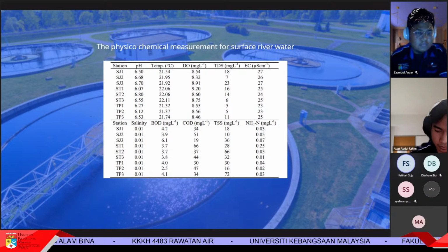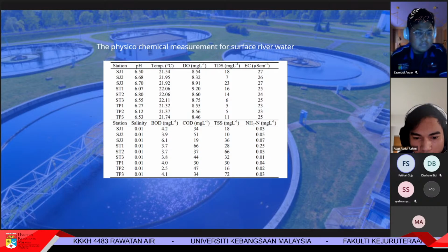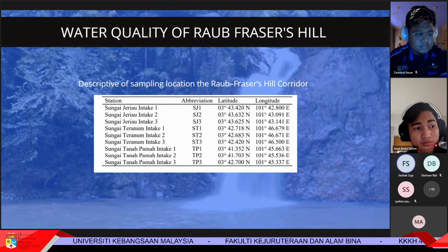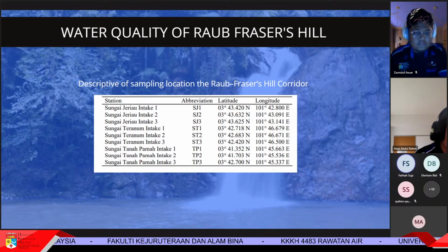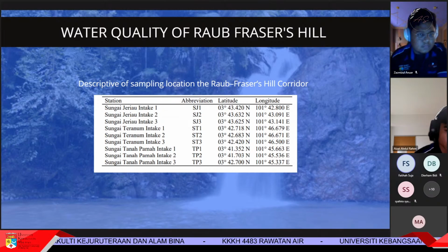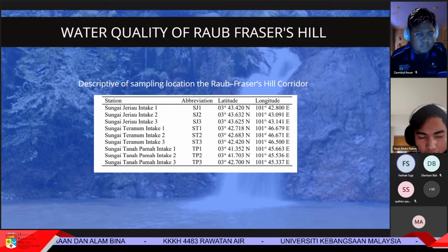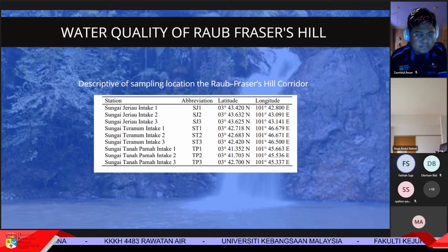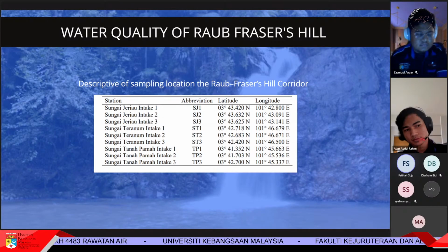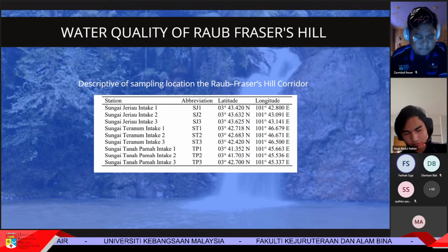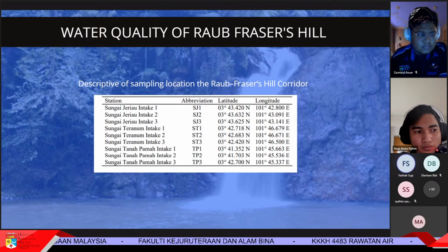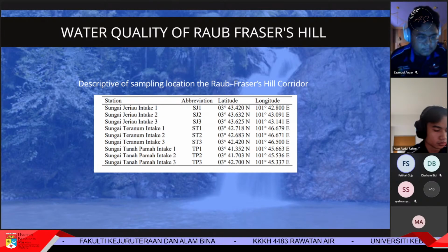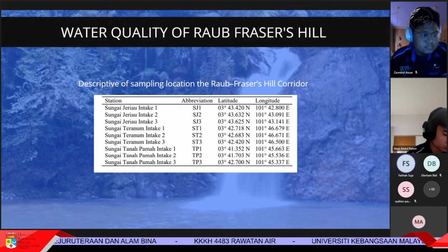Actually, they are basically very clean water. You can see from the dissolved oxygen. So for this treatment plant, if possible, I want you to have something more than what is required. Some of the parameters need to be in class 3, so that you need to do extra than what the conventional treatment plant requires. Since you have chosen this river, I hope that, based on what I taught you last time about coagulants, you also have something new, not only taking what the conventional process is. Like maybe a natural coagulant that you use instead of aluminum sulfate. Okay, group 9?